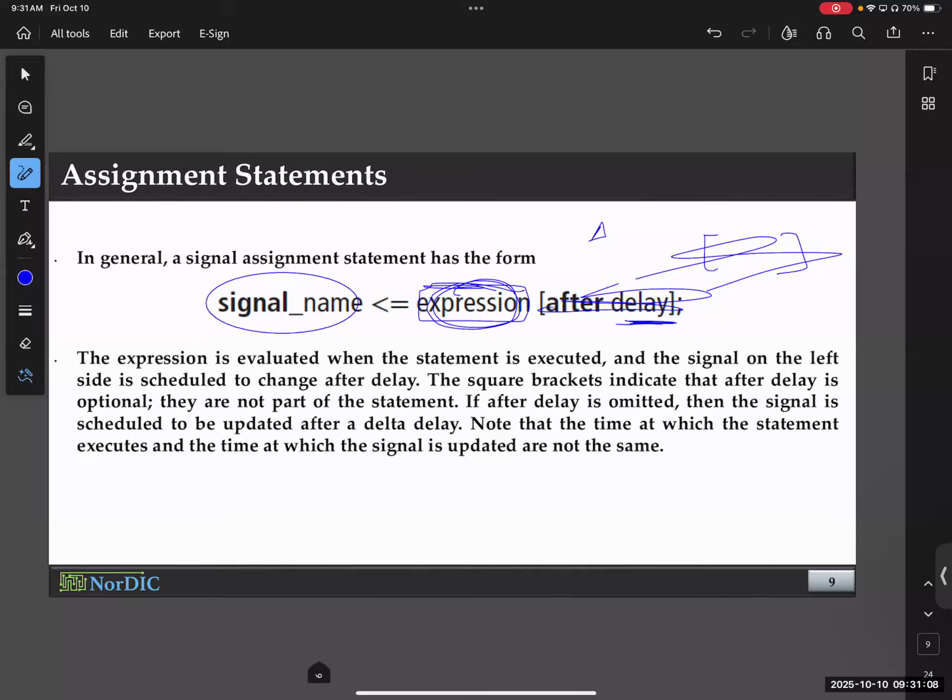Do you see what I'm trying to say here? Once I know this, I can always include it in the code. And I am responsible for making the VHDL component for the multiplexer. Towards the end of this lecture, you will see there is a library. You don't have to do it from scratch every time. You're learning it, but you probably don't have to ever do it. You can always use things from the library.